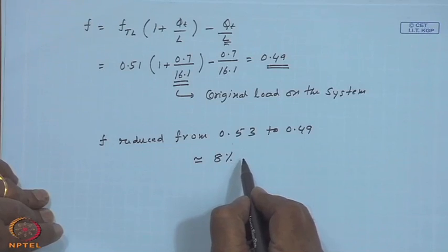Whether the guess temperature is correct or not is found out by obtaining what we call the average utilizability, which corresponds to some sort of an average x c bar, which should correspond to an average inlet temperature to the collector. So, the suggested possibilities being T minimum equal to 60 or whatever, and this T I bar, we take the average, and if this average is close to the guess that we made in the beginning, then we will stop the iteration. Otherwise, you take the new value that is obtained and go through the procedure again. So, this is how the tank losses can be taken care of.